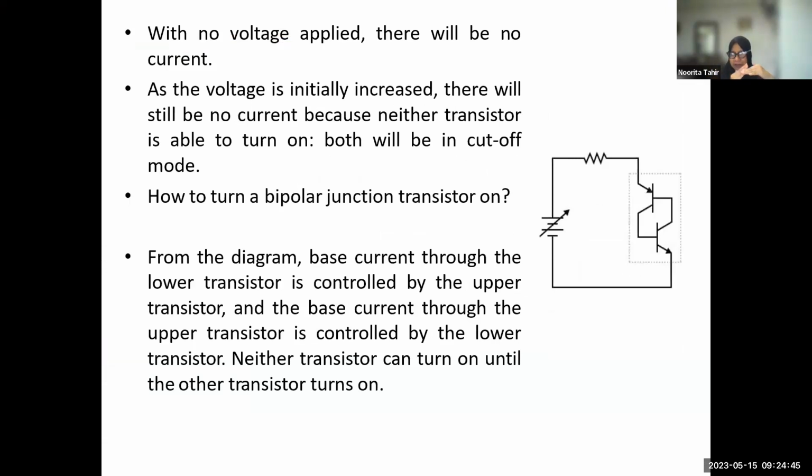Real transistors, on the other hand, have defined limits to how much collector-emitter voltage each can stand before it arrives at breakdown. Remember, we have the threshold voltage, and that depends on the type of transistor, whether it's silicon or germanium. But normally we will use silicon. That's the normal one. V threshold is around 0.7.